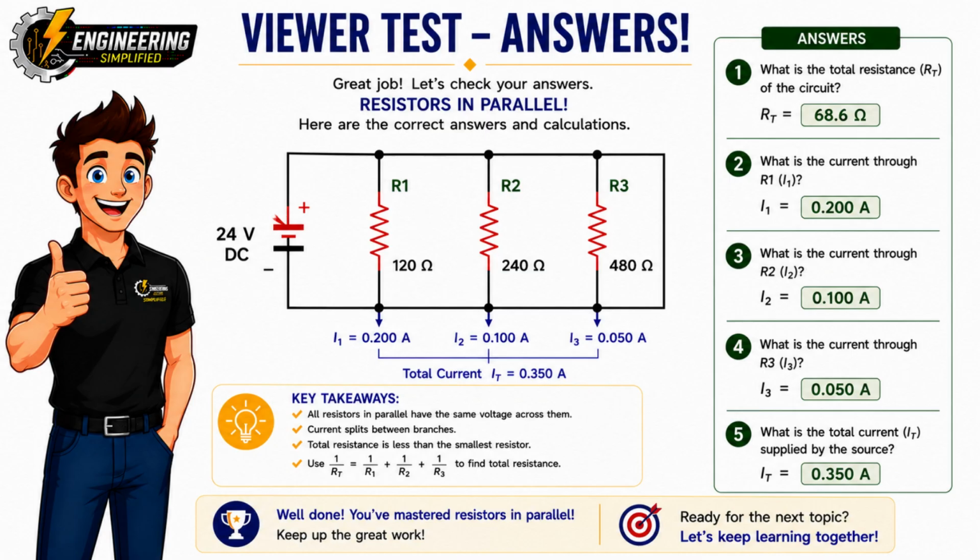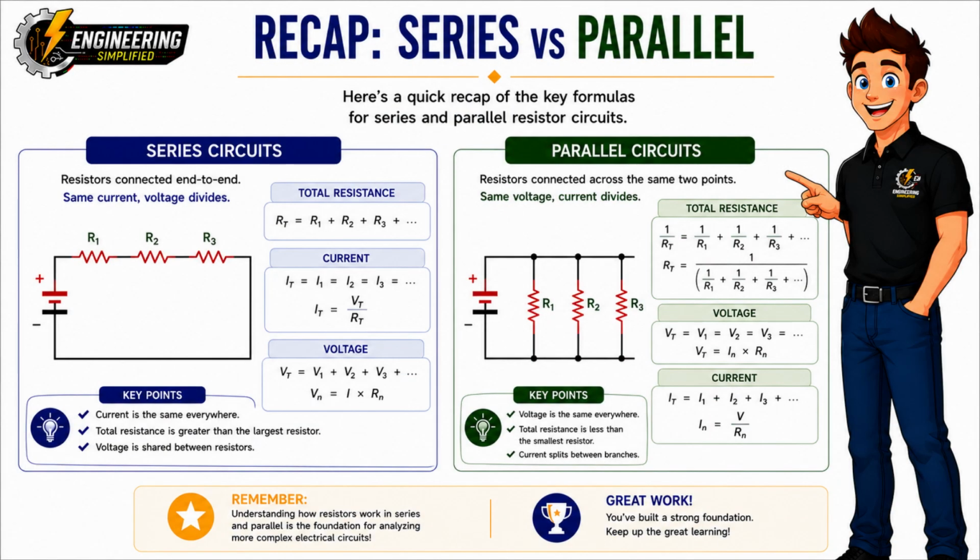The important things to remember are these. Every branch in a parallel circuit has the same voltage across it. The current divides between the branches according to each branch's resistance. The total current is the sum of all the branch currents, and the total resistance is always less than the smallest resistor in the network. Now that you've mastered both series circuits and parallel circuits, we're ready for the final stage of this tutorial, mixed circuits, where we'll combine both methods to solve more realistic engineering problems.